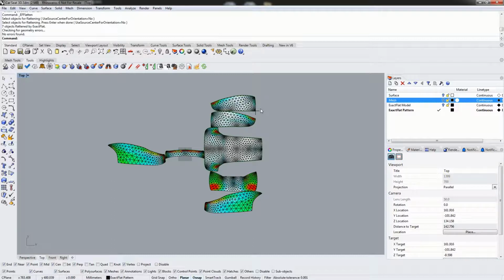Because they are very, very fast pre-flatteners, it's much better to eliminate as much strain and sag as possible using the pre-flattener, and then finish the job using the optimizer. The performance and the amount of time required to use the optimizer depends entirely on the shape and the amount of strain present in the pattern piece being optimized. So if we can use a very fast pre-flattener to reduce the strain before optimizing, we're going to save a lot of time when we start using the optimizer.